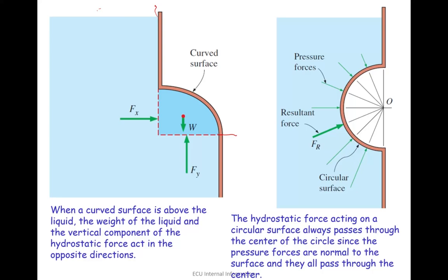If we assume this plate is very thin, do you think water on this side gives the same pressure on the surface compared to when water is here? Yes, whether we assume water on this side or this side is the same, it doesn't matter, as long as we assume this plate is thin.